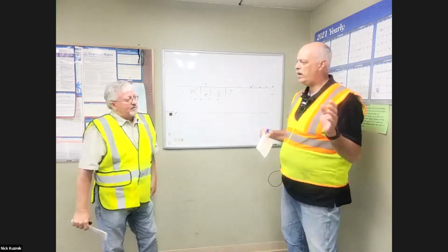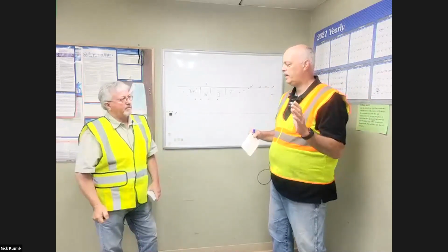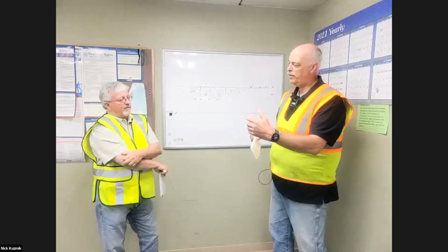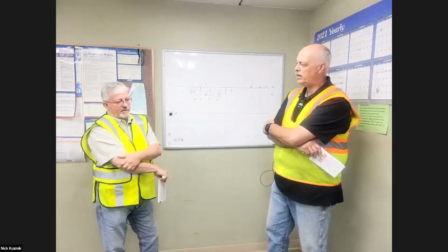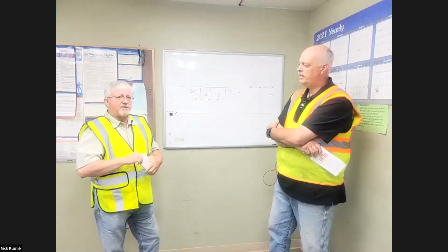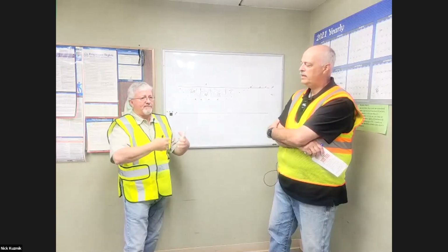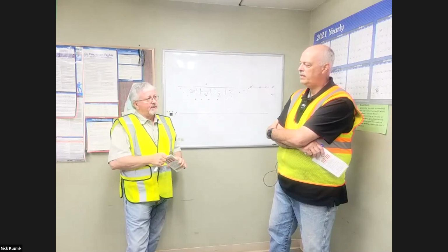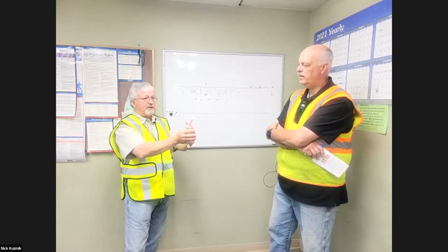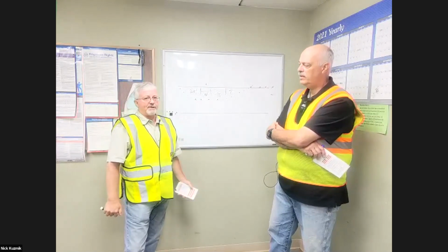A lot of guys have a lot of country roads that are winding and twisting, and you said something about a hill, but what happens if you have a long curve? How far back do you want to go to catch that? As far back as necessary. You want the drivers to see that person approaching the work zone, and to give them that information so they slow down. So you'd move the flagger and all your signs beyond that curve to where the line of sight is pretty good. Stop them and slow them down before they get to where they have to slam on the brakes.